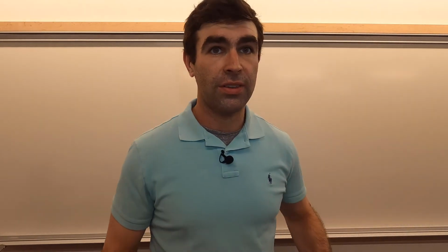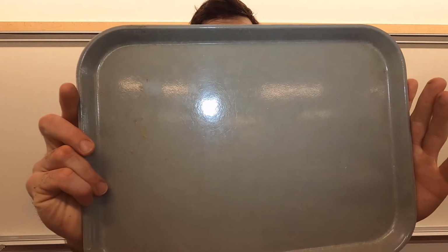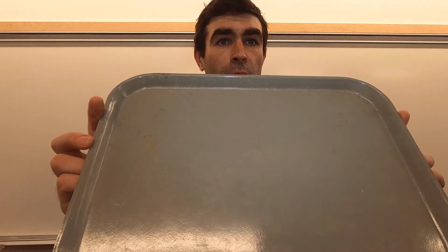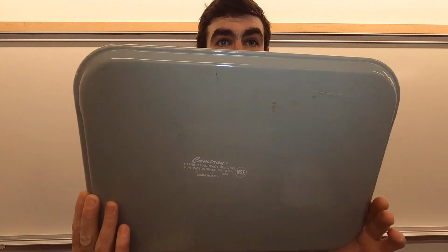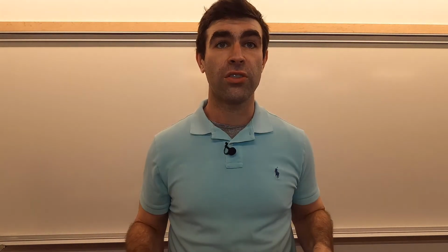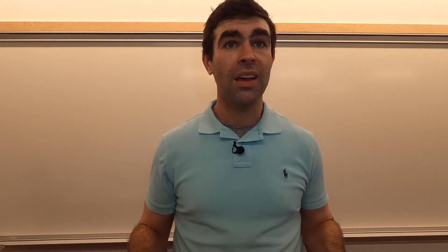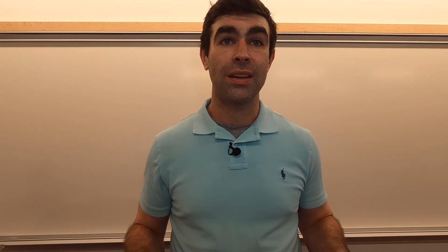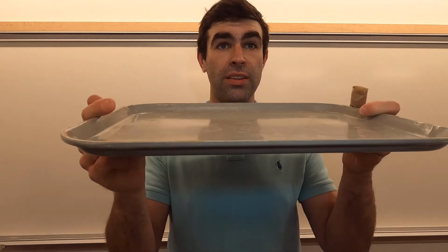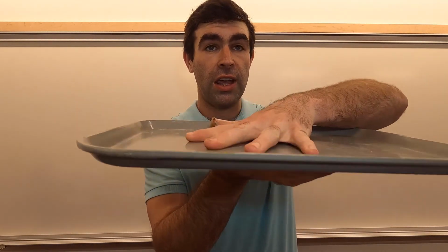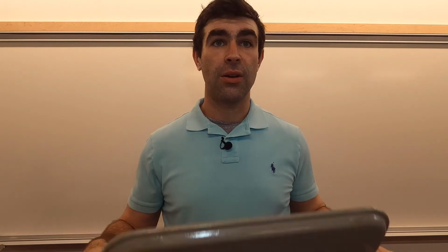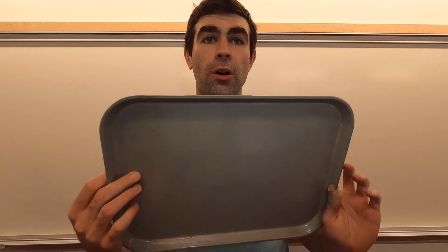Don't have a ton of examples, but this tray is something that was definitely compression molded. This is fiberglass, right? So what they did was took a sheet of probably prepreg fiberglass that already had resin in it, put it between the presses, crushed it into this shape, and then heated it, and you have a fully formed part.